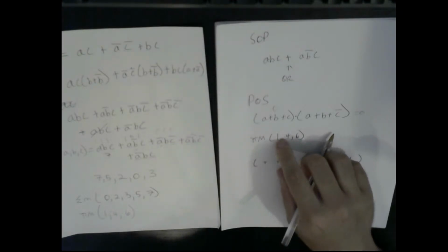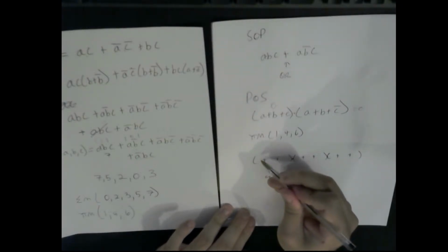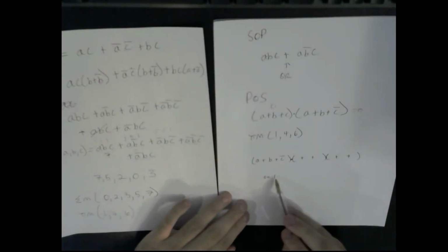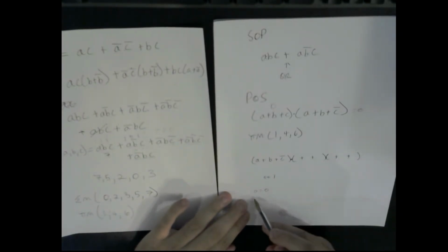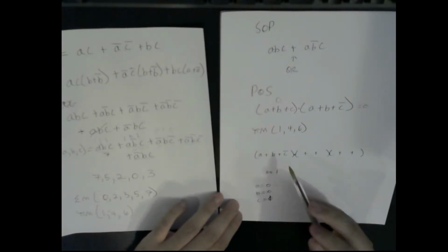So I have 1, which means if I have a 1 in my equation, I want this term to go to 0. So how am I going to do that? Well, 1 is represented by 0, 0, 1, right? So what I'm going to do is say A, B, C naught. How did I come up with it? Well, what I thought in my mind is, if A is equal to 0, B is equal to 0, C is equal to 1, I want to make it so this is going to equal 0 in here.